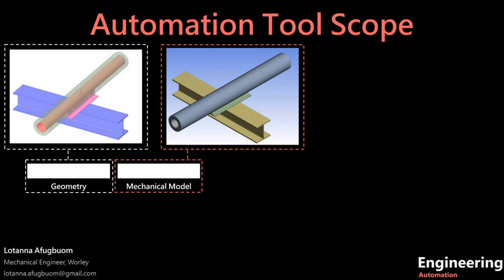After meshing, the FEA model is transferred to the steady-state thermal component from the mechanical model component. Within this component, thermal loads, such as the ambient temperature and the ambient convection loads for pipe, shoe, and beam are applied, and finally, the pipe bore convection load defined.